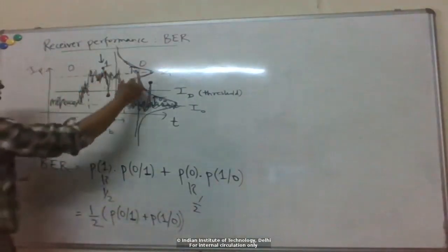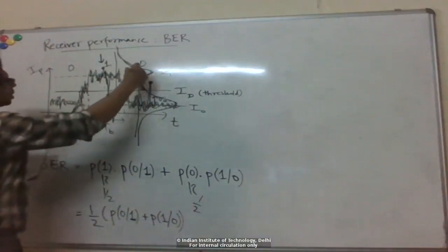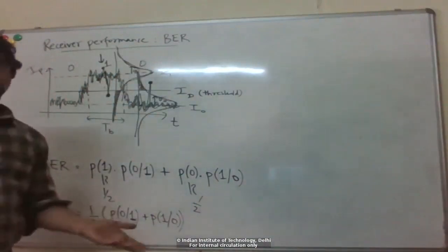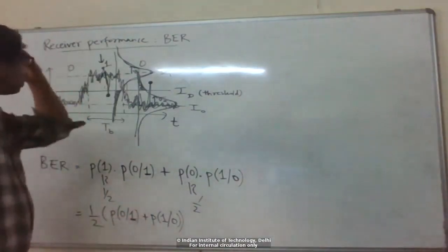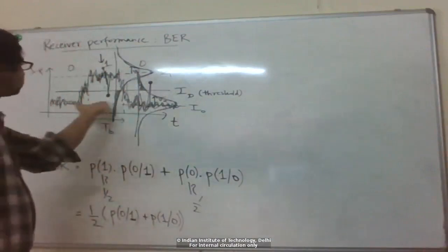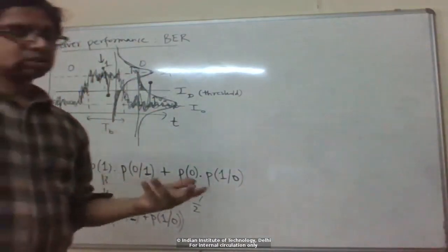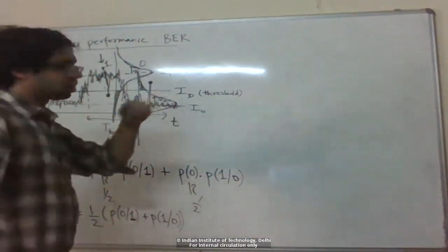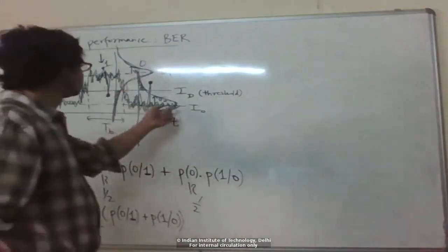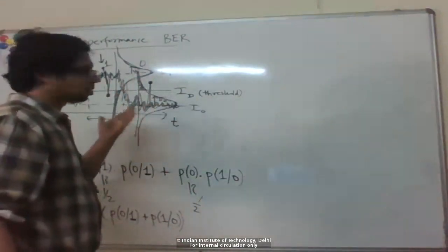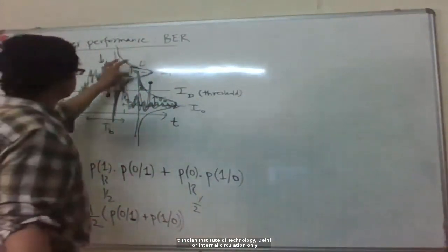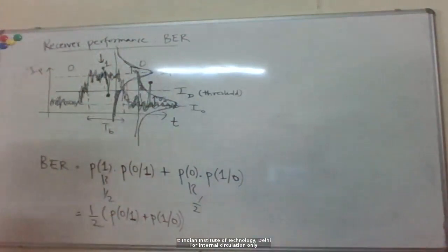From here you can see that the noise is assumed to be Gaussian. For thermal noise, it's true, it's Gaussian noise. And for shot noise, we saw that if the average number of electrons per unit time is large, much bigger than 1, then it is also pretty close to a Gaussian. So in practical cases, this is quite well modeled by a Gaussian.